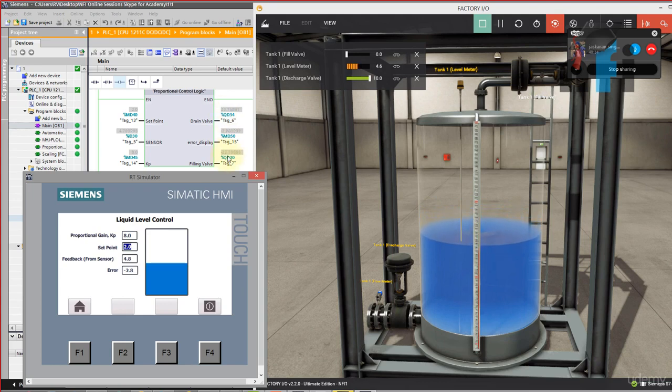So when it comes in the range of 0 to 10, you will see the valve. And these values of minus 14 and 13 are not recommended. You should have the range 0 to 10. Now this value is in range, so you can see the valve is here. So how to avoid that? We have to write the limits in our program. The limit says when the value of valve is more than 10, the valve should have the value 10. The maximum limit of the valve should be 10. Similarly, minimum limit should be 0.